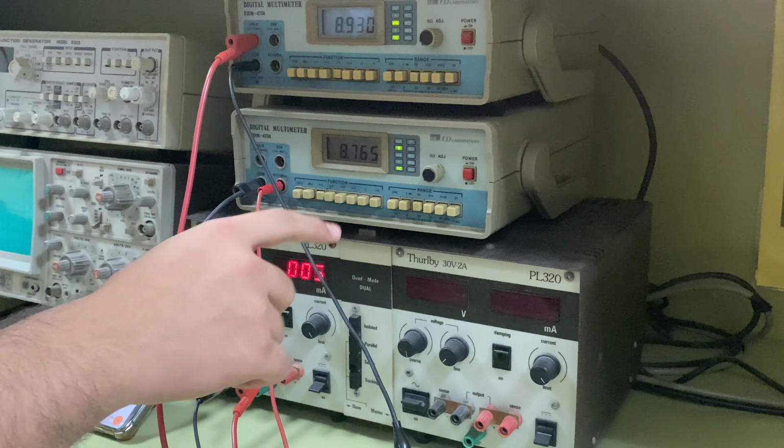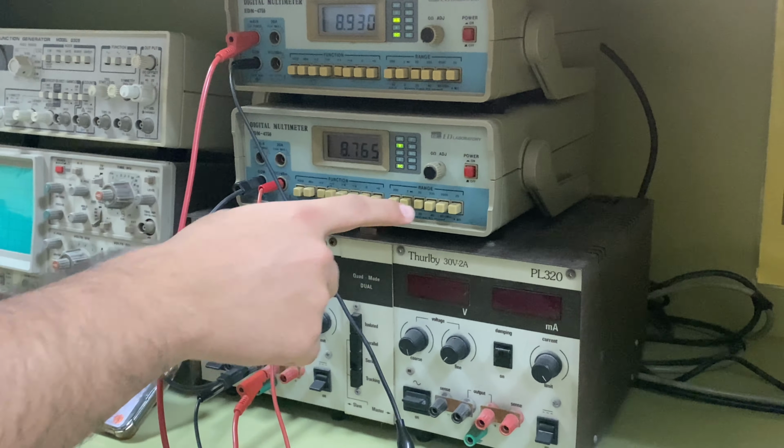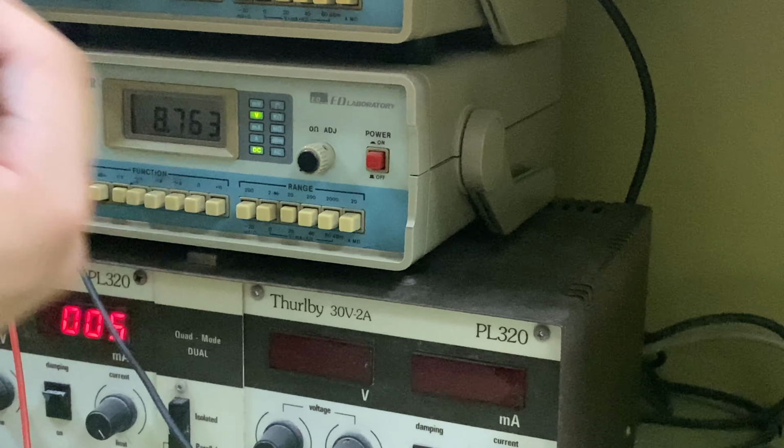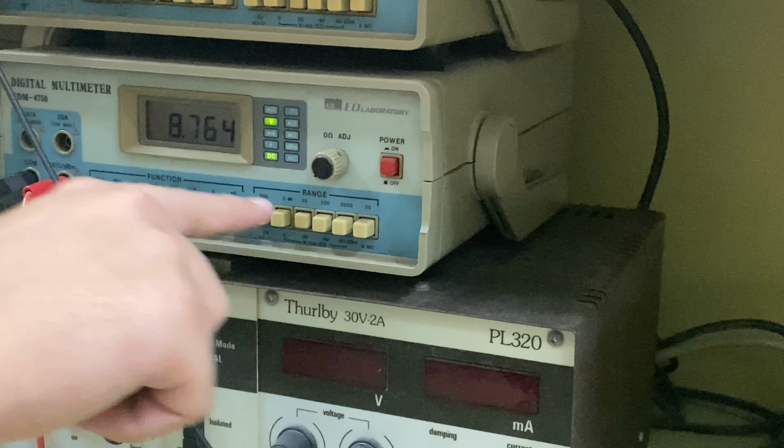For the next multimeter, we connect it as a voltmeter. And as I explained in the first experiment, we plug the positive terminal in this plug. And always, as I said, the black one is for the common, which is the ground. Next, we choose the proper function, since we want to measure the DC voltage. We choose this one, and we choose the proper range, as I explained in the first experiment.